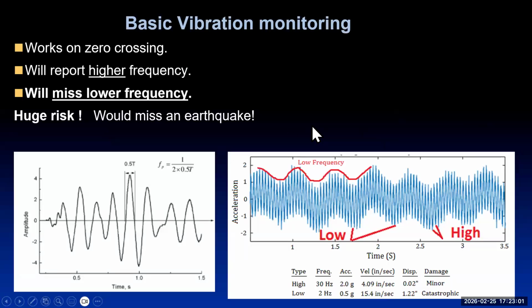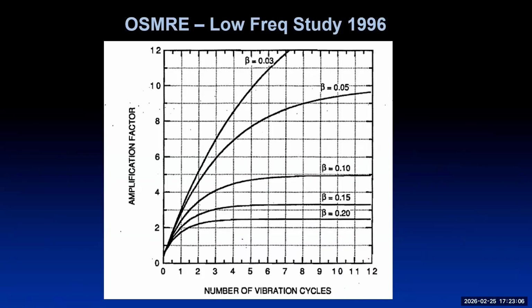So here's another. I can add to what you're saying about the minarets. The mass which is participating in their vibration has to be small, in the same way as chimneys are small, whereby you have a windshield around the outside of it, and that's all. That's all the mass there is. Now, I've made measurements of very tall chimneys to find out what the damping is. And you're talking about, yeah, they were probably around 1%. I measured at